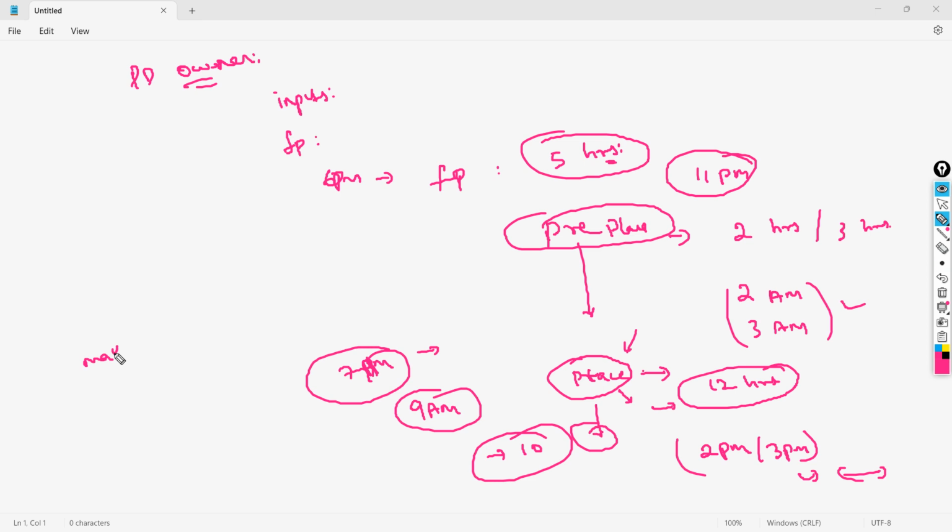Say for example, if I say make route, or I just want to fire the route immediately, it would run each and every stage. Say you have a floor plan, placement, CTS, and then route. I just want to execute the last command, and all these stages should get automatically executed. First it should run FP and then place, etc. So the make based flow helps in going back and checking whether the stage is completed or not. If it is completed, fine, it goes and runs the next one. If it is not completed, then it reruns the whole thing, the FP, and then continues.